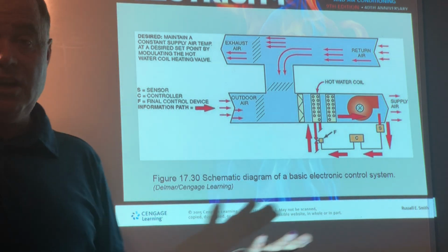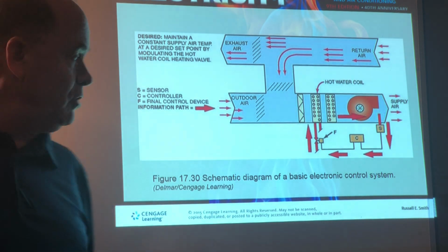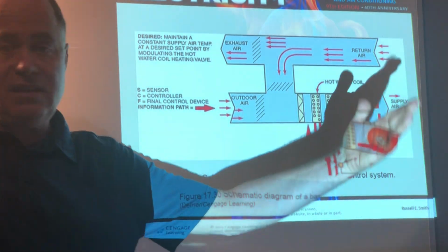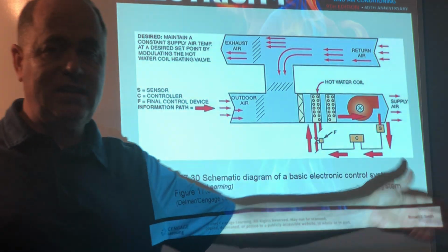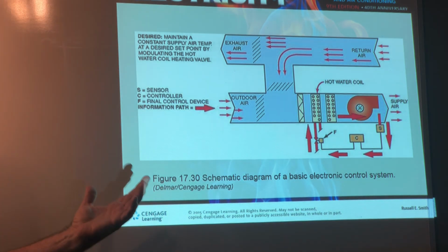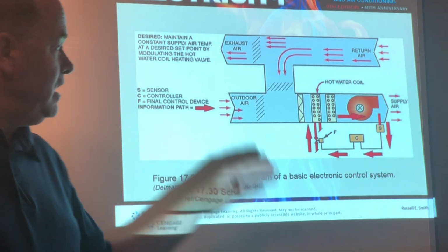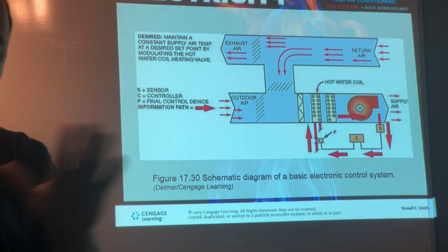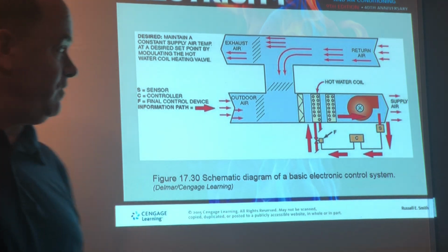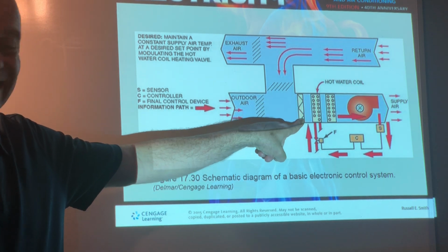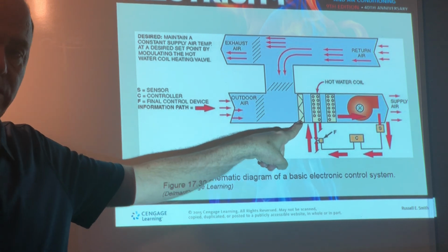Or sometimes 100% cool air, called Economizer Mode, where when you have a bit of a load inside, it's 75, 76, 77 inside, but maybe it's only 60 degrees outside. You want to provide some cooling early in the morning. You can open up these dampers and flush the building with cool outside air, not having to run your expensive chillers. So here you've got your outside air, and this symbol here is actually an official ASHRAE symbol on a blueprint for an air filter,